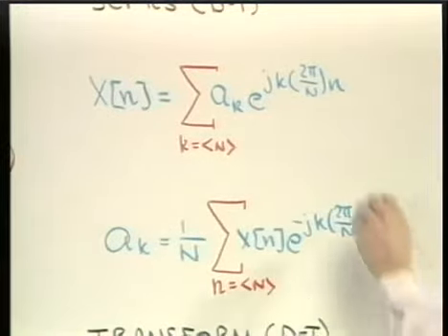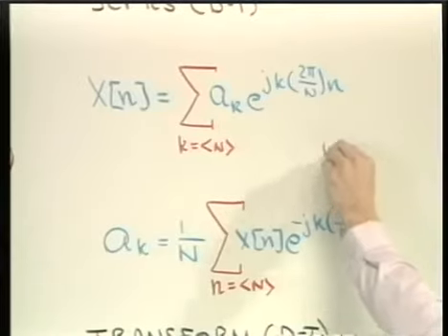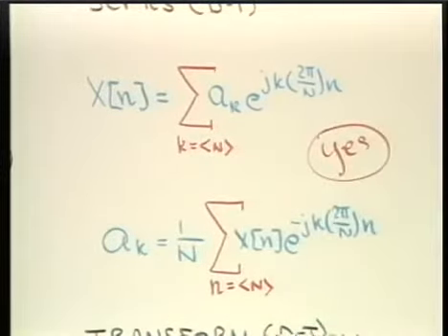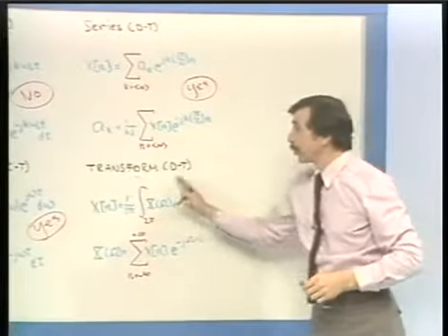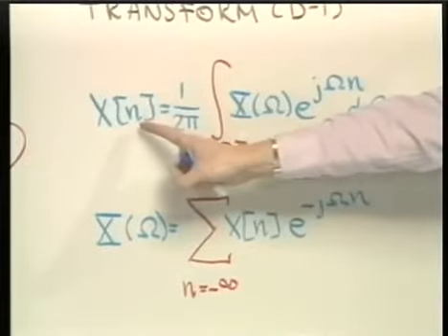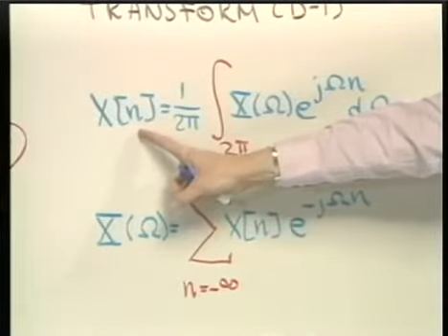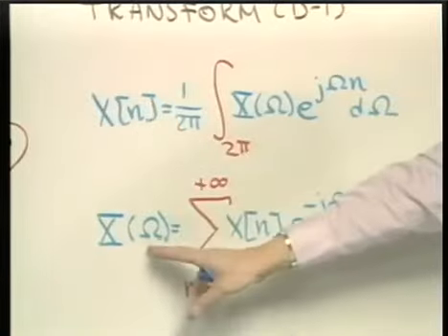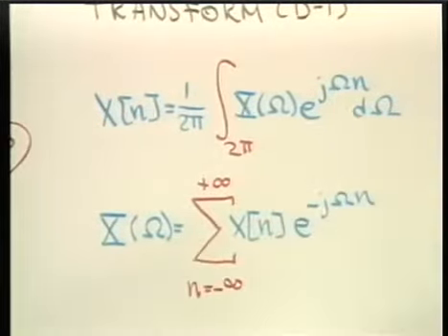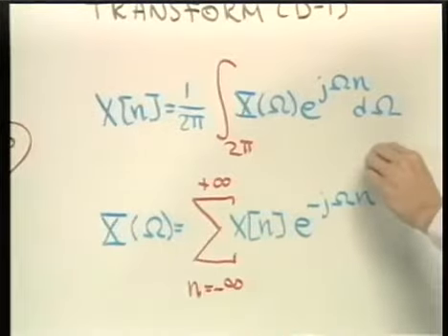And so it's the discrete time Fourier series that has a duality. And finally, the discrete time Fourier transform loses the duality because, among other things, in the time domain, things are inherently discrete, whereas in the frequency domain, they're inherently continuous. So, here, there is no duality.